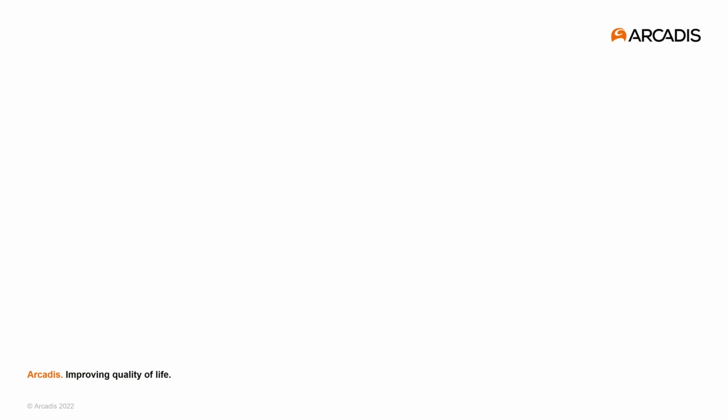So the high number of iterations is, in my opinion, an indication that there's a lot going on in the structure at a lot of places, and not necessarily at your failure location. If you have one clear failure location and nothing happening elsewhere, then normally you won't need this many iterations. And if you need many iterations, it's because there's a sudden change in something. So a sudden crack opening, then you have one step that doesn't find convergence, and then the next one picks it up again.